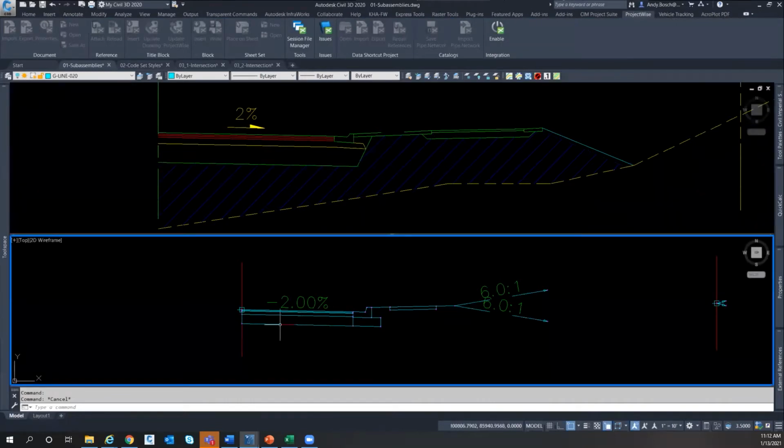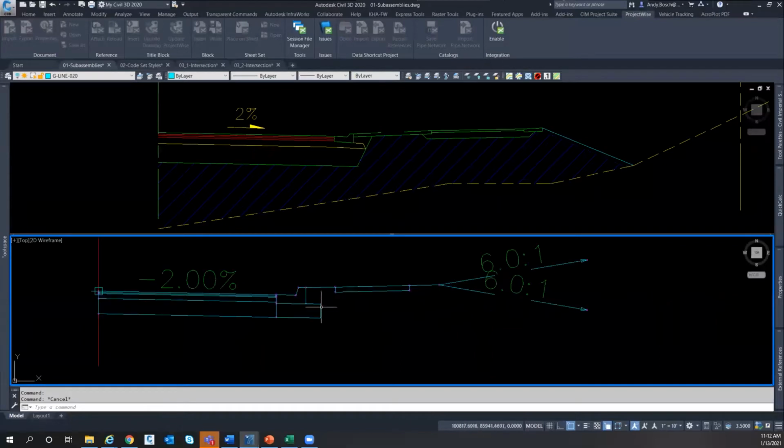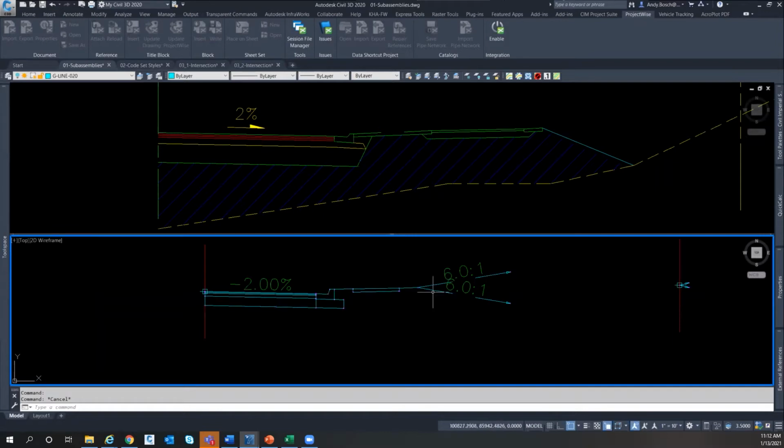And with this out-of-the-box subassembly, you can start seeing where we're a little delinquent on what it could build. Like our curb definitions aren't giving me that layback slope. I'm not getting definition for topsoil placement. And then we start moving to the right and we start getting into daylight assembly.